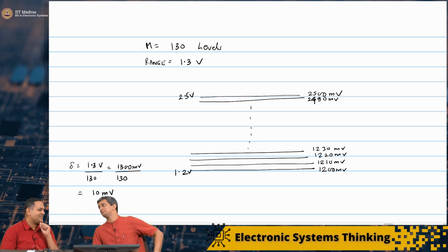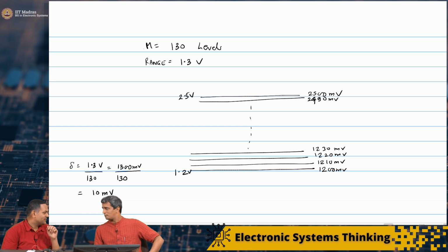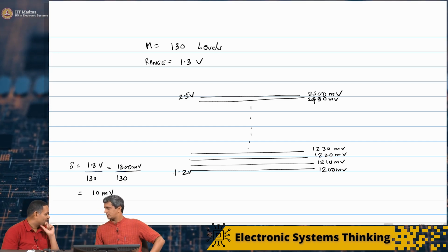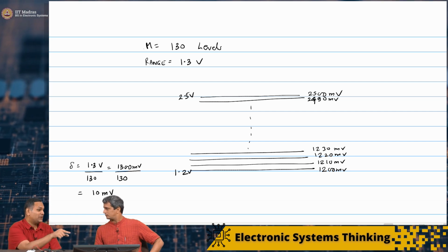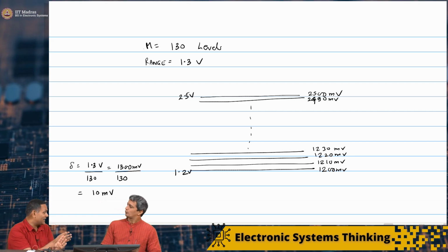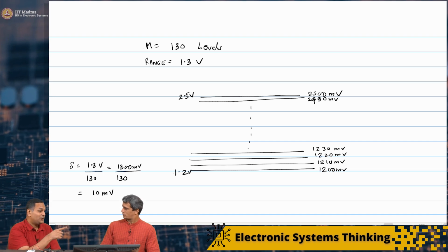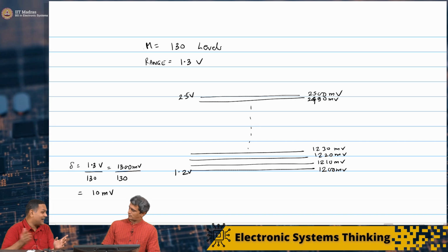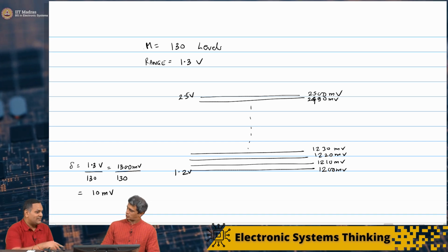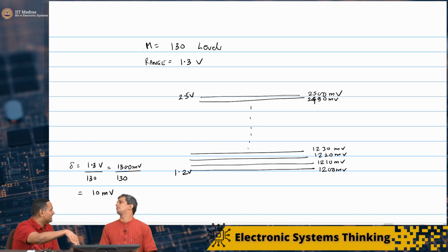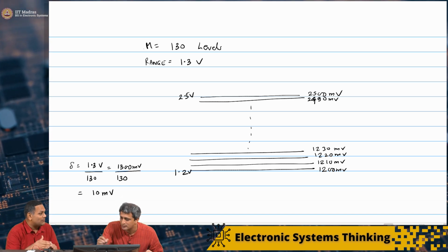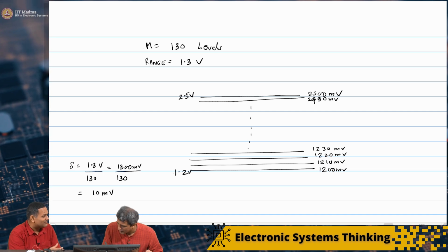Okay, I see now. Which means if I quantize it like this, and if I took a sampling, so I'm now trying to tie back to what you did in the discrete time. If I took any one of those x of 0, x of 1 all the way to x of n times ts, which is what you wrote, they will lie on any one of these lines. They will lie somewhere here. And if you decide to do amplitude quantization, you are going to tie it to the nearest level?